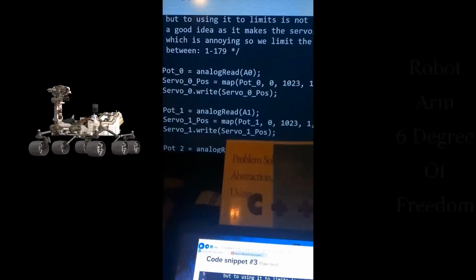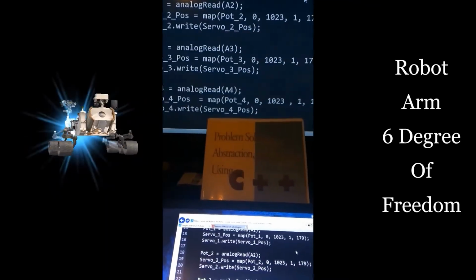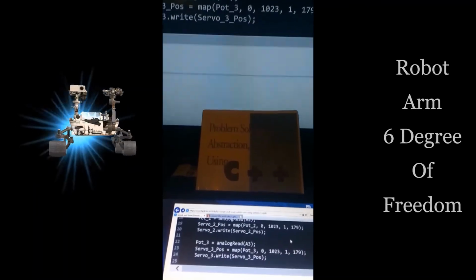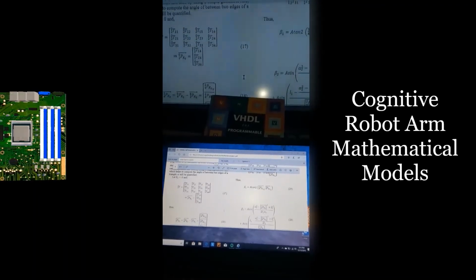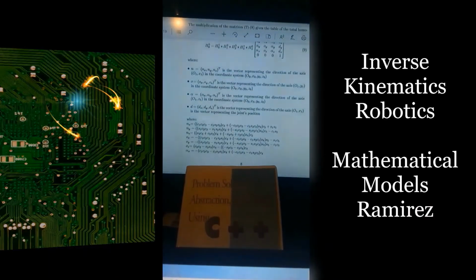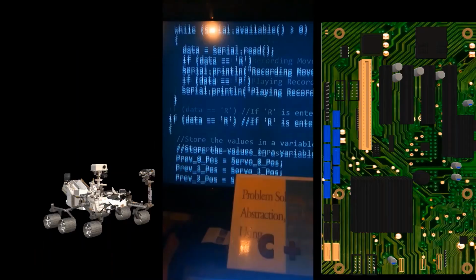Using the kinematics equations to find the desired position of the end effector. Forward kinematics uses the joint parameters to compute the configuration of the kinematic chain, and inverse kinematics reverses the calculation to determine the joint parameters that achieve the desired configuration.